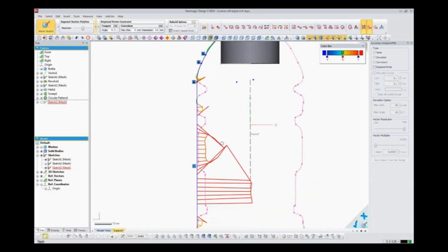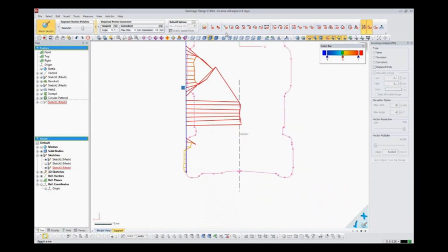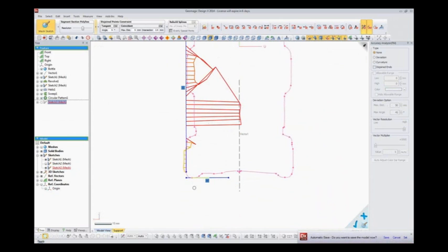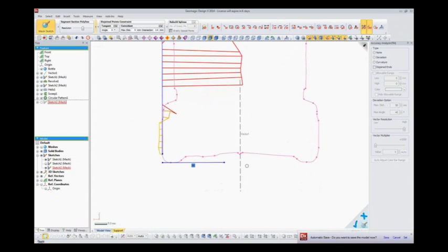Okay, and on the bottom, again we do something like this. Put it here, and get the center line, construction line. Then I'll extend this one to the center line and do a corner trim at the edge.